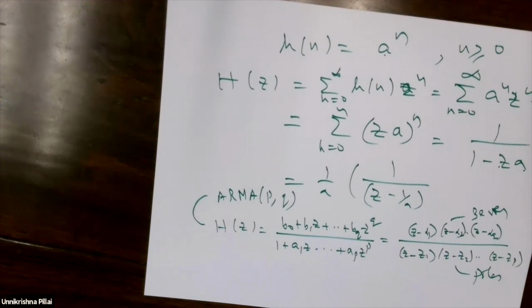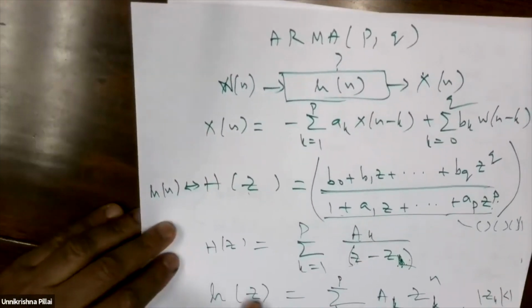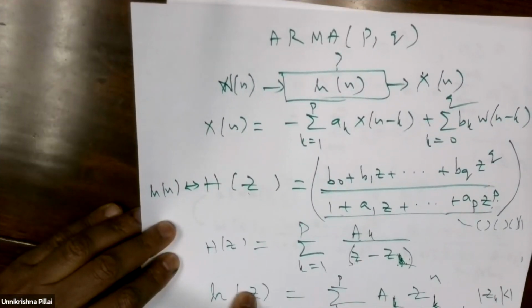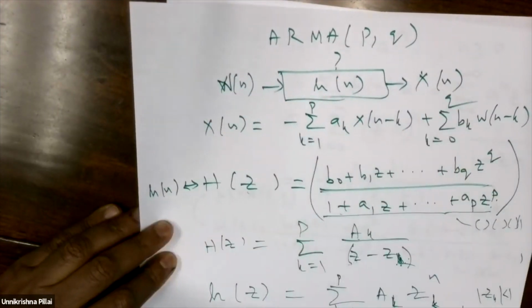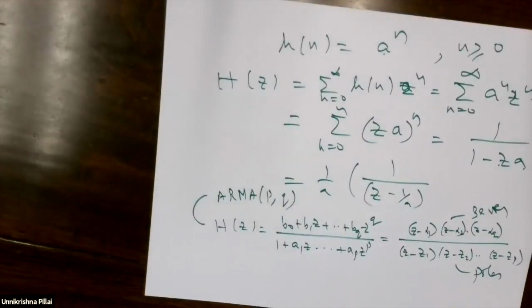So remember, the autocorrelation function of the output, you can write it in terms of the impulse response, which I gave to you here. So it's a linear time invariant system. You know the impulse response. Then the impulse response convolved with the input autocorrelation twice will give you the output autocorrelation function, if you want to go that way. But I have done this in great detail in my lecture 14, so you should see this, but now it should be easy for you to read.